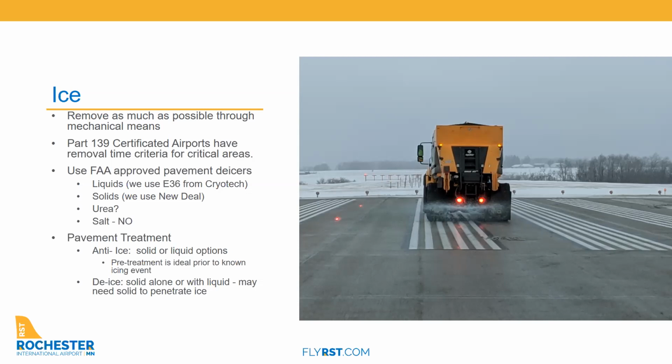but in the end, I still would put the chemical down with a chance of freezing rain and deal with it if we just got snow, because breaking that bond, getting that liquid down so that ice can't bond to your pavement is extremely important. Again, all operational need-based. Some won't have a need for that, some will. But if you can keep that chemical down to keep the ice from bonding to your pavement, that's ideal.